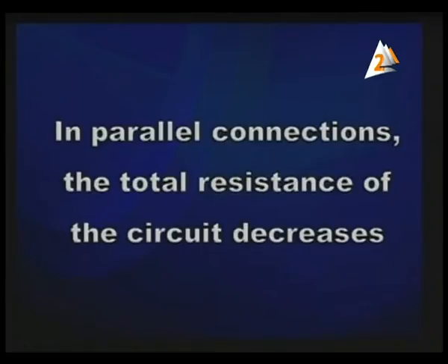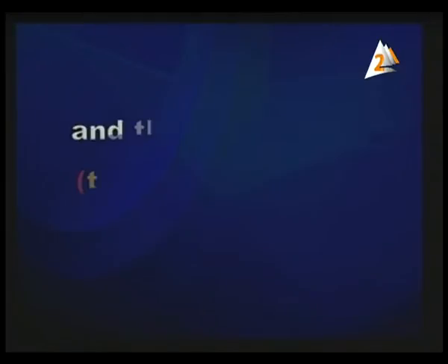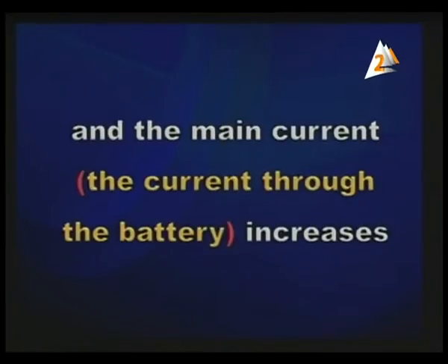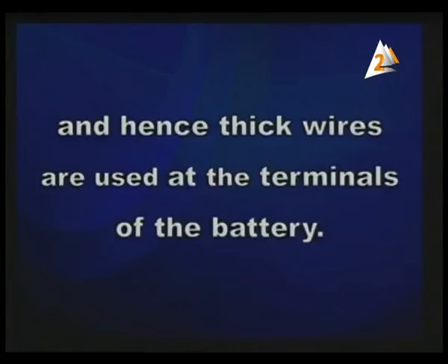We all agree on this. And what about the effect of this on the main current through the battery? Of course, it will be increased. So in parallel connections, total resistance decreases and the main current, the current through the battery, increases. Hence thick wires are used at the terminals of the battery.